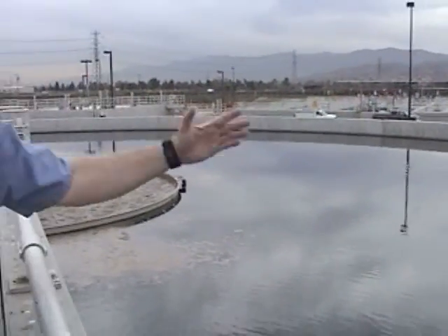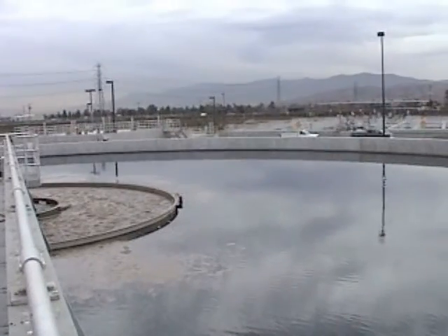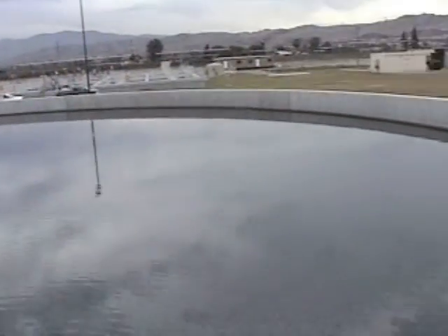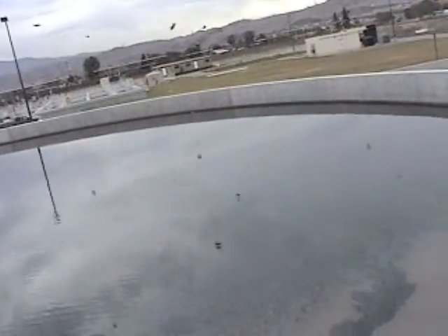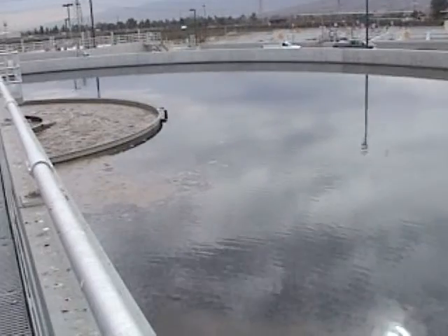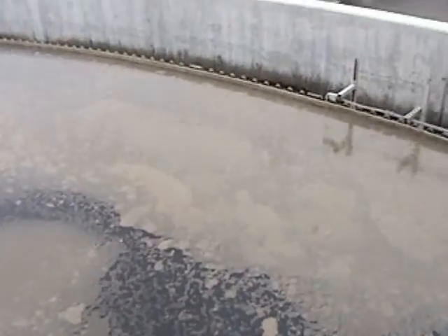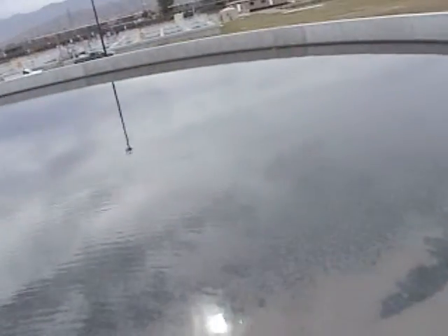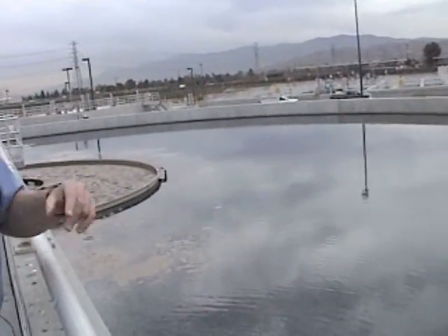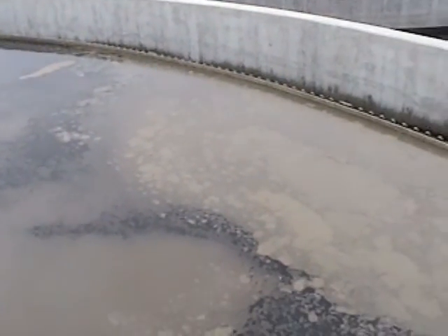The problem you have here is you are picking up a little bit of Nocardia foam off the aeration basins. It's getting in here, and as the sweep is turning just a little bit slow, it doesn't have a chance to get over, so basically you're picking up a little bit of debris between sweeps. Rather than rotate this down and return a whole lot of water to RP2, which is what we'd be doing, we just let this system handle it. We could probably look into speeding up the sweep because we are picking up a little bit of debris on the surface of the water. Normally we'd like to have it looking perfectly clean.